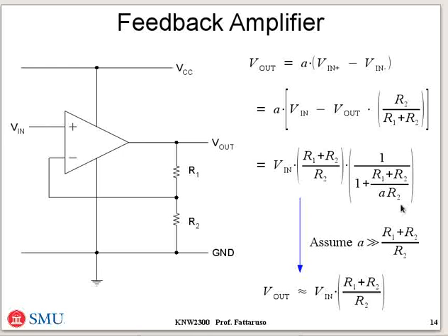So basically we can just cross out this whole term in this expression, and we're left with the output voltage of this circuit block being the input voltage times a new gain factor, which is just determined by the ratio of resistances of the passive resistors in our feedback network.